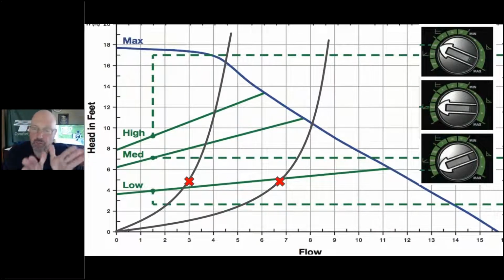All right, so just remember, it's not designed for zone valves. The automatic modes, the learning modes, not designed for zone valves. All right, you need to have those proportional style valves or proportional flow designs in your systems in order to take advantage of that mode. I hope that makes sense.